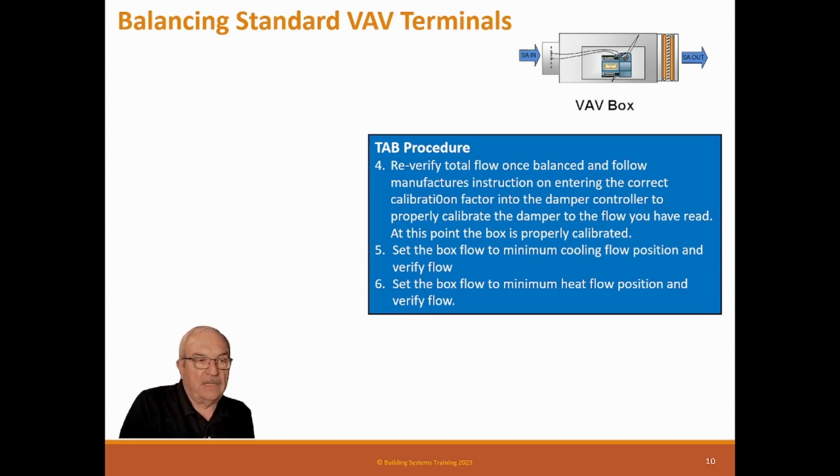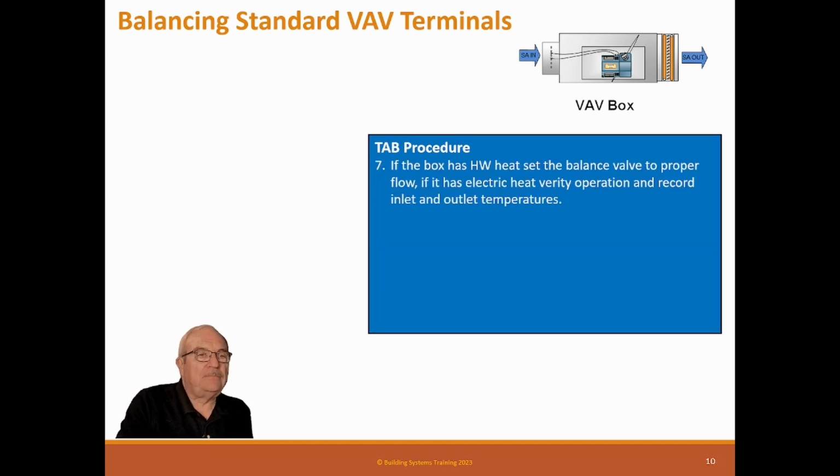If that's the case, reading the grills at low flow is helpful. Otherwise, it doesn't make a difference. And then set that heating flow. We have never actually read heating flow, but you could. It just makes the form really complicated to have full preliminary flow, full flow, minimum flow, and heating flow. It would be lots of flows to have on a form.